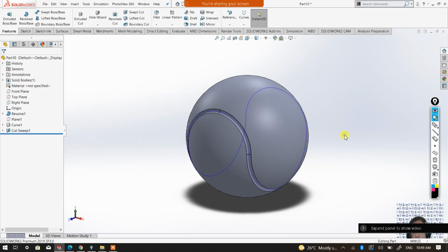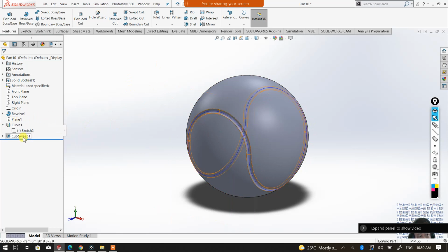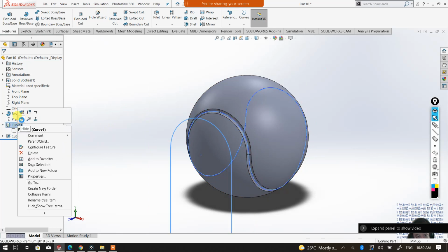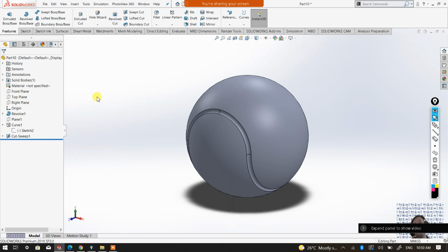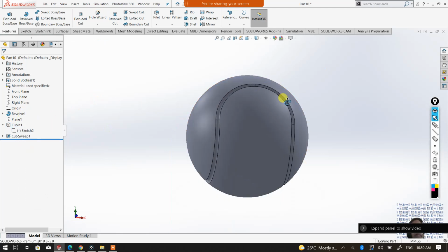There you are. Okay, if the blue color is there, same as what we did for the spring earlier, it means that it's something to do with this sketch. So right click, oops, sorry, not that one, click this one, it's under curve here, so click this curve and then hide. There you are. Okay, curve here, right click and hide. Alright, so now we can apply.